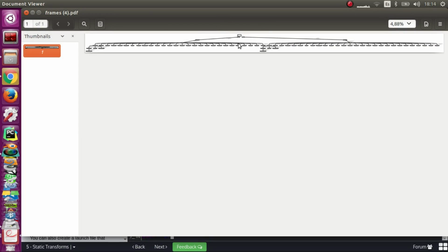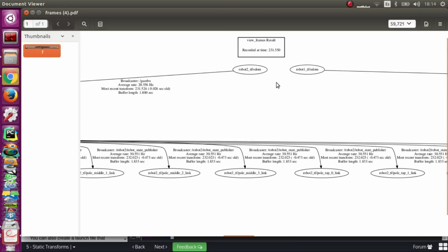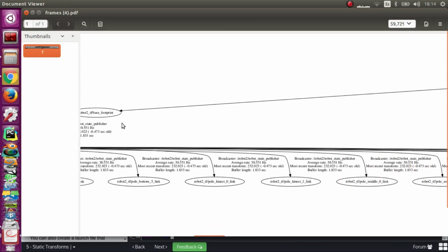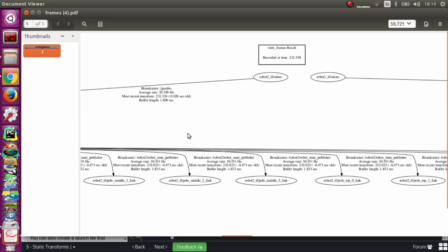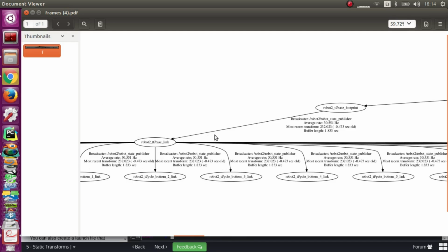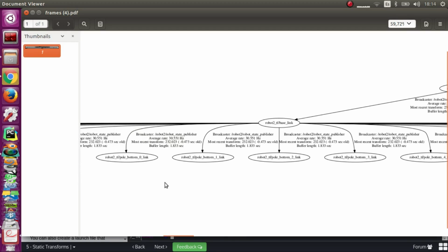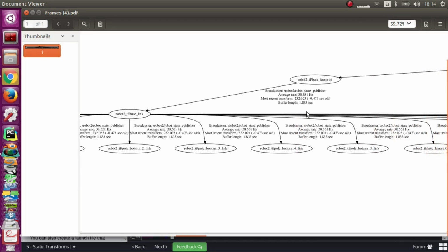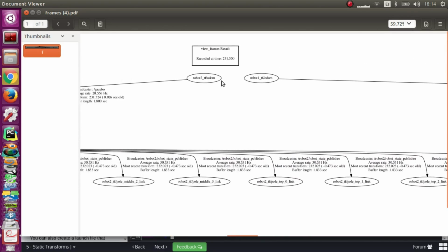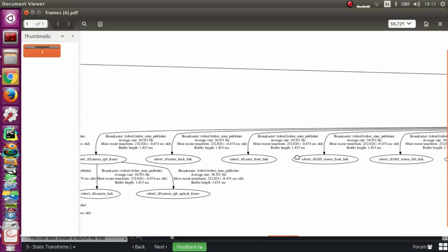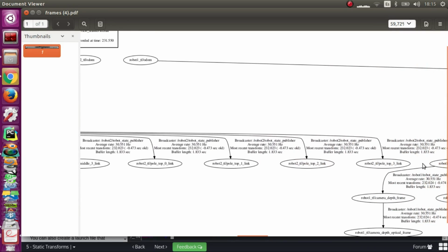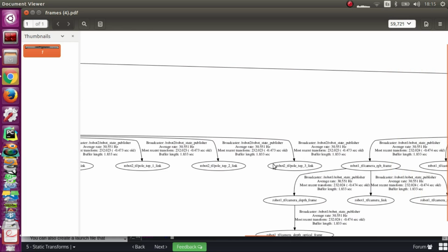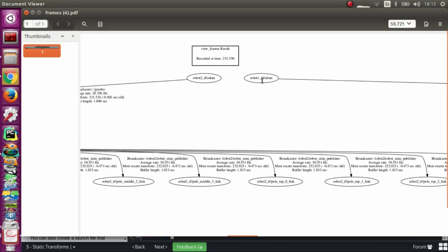Well, this is quite a complex one here, but you see quite fast what happens. We have the robot 2 and the robot 1, but they're not connected. Everything else is published, all to the base footprint and so on. Why? Well, basically this is a robot that doesn't have any moving parts, so it's really easy. But they're not connected. That's why we can't publish the TF of both robots at the same time. So ROS doesn't know how to do the transform from this odom frame to this one. So it can't represent this element from robot 1 in this one in robot 2. It can't, because it can't go here. It's not able to make this jump.